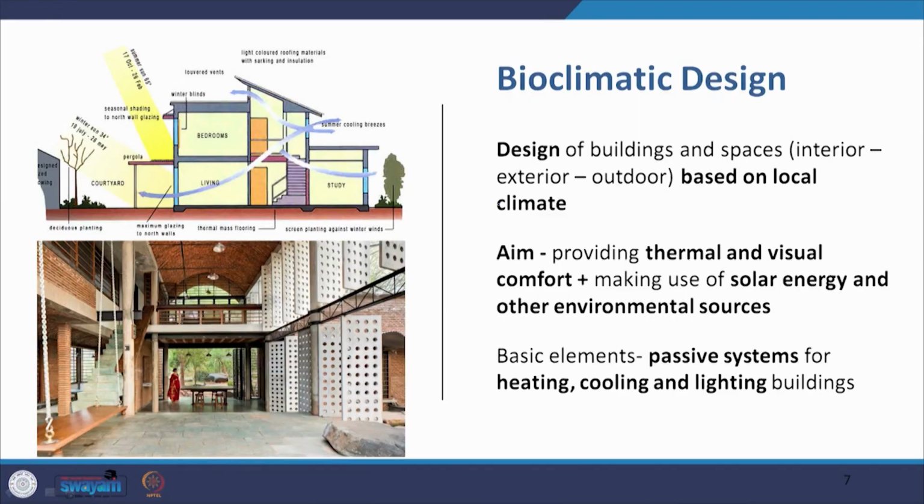Now what is bioclimatic design? That is the design of built spaces based on the local climate, and the aim is to provide thermal and visual comfort by making use of solar energy and other environmental sources. So if I were to take a section of a bioclimatic house, it would have the breeze flowing in, the use of sunlight, use of proper shading devices, etc. Use of, for example, this kind of louver vent here at the top to allow for the hot air to move out of the building.